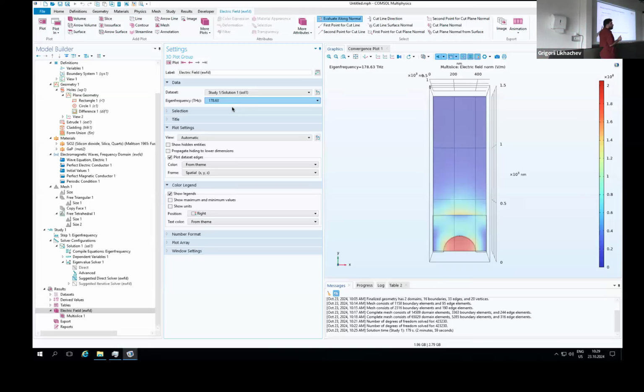This is the S11 parameter that you would get from the port that you put in your FDTD simulation. The phase of this parameter is the green one. You can just take the real and imaginary part and get the phase out of this S11 parameter. It's very straightforward.